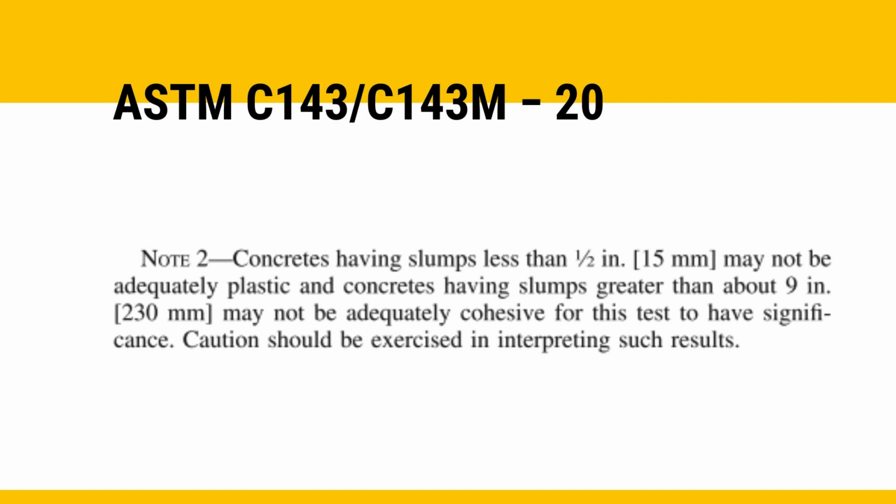And during the experiment, the slump height that we got is 1.2 inches, which means the concrete mixture passed the slump test, since according to ASTM C143, the minimum requirement for the slump height is 0.5 inch, thereby it met the standard.